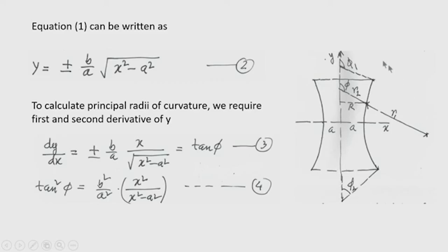So, this type of shell is an example of an anticlastic shell, which we have not analyzed earlier. We earlier analyzed shells which are doubly curved of course, but they were synclastic in nature, and in one case we found that the Gaussian curvature is 0. Such a shell is formed by rotating a straight line, for example the cylindrical shell or conical shell that we found earlier.